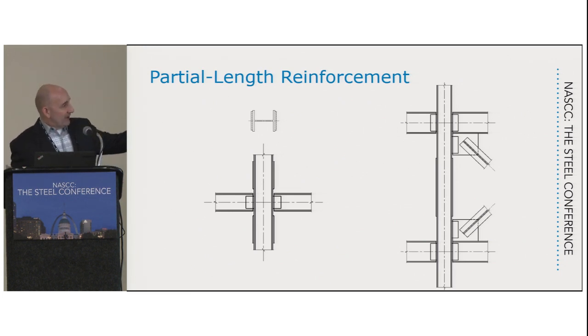Okay, but when you get something like this, which is usually the case for me because I have vertical brace gusset plates I have to contend with on most every project, the right-hand side there, you will end up pulling your reinforcement back maybe 50% of the distance between work points from here to here. And typically, if I can get by with it, usually I'll just put the same plate on both sides. Even if this one can run all the way up, usually I just give them the same plate.